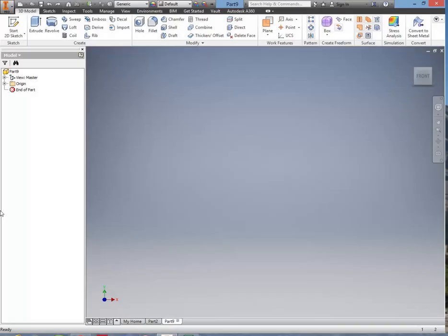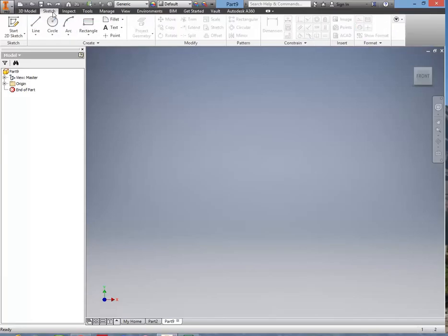The next step is how to start a new sketch. Now, Autodesk Inventor is a 3-dimensional modeling and computer-assisted design (CAD) program. However, for the purposes of this module, we'll be using it in its 2-dimensional form. So we're going to be using the Sketch command, and I'd like you to click on the Sketch File menu here. Once we click on it, we will see our basic drawing commands, and we'll see a Start 2D Sketch.